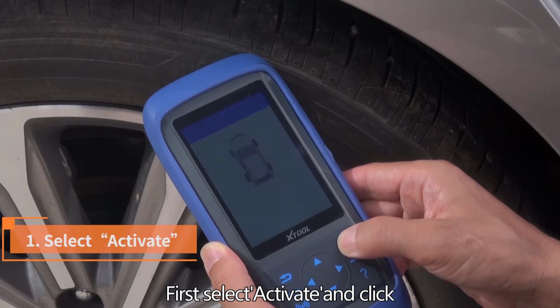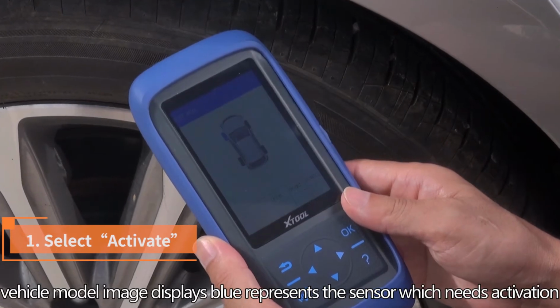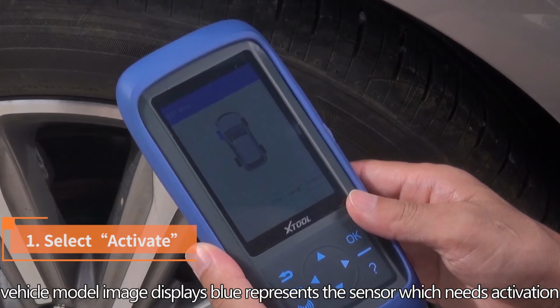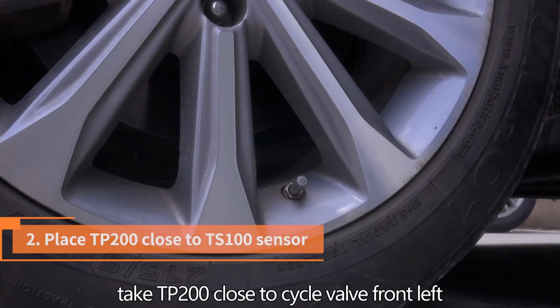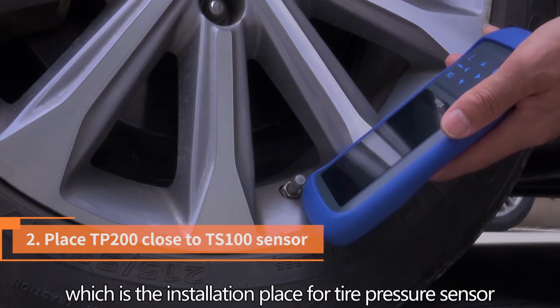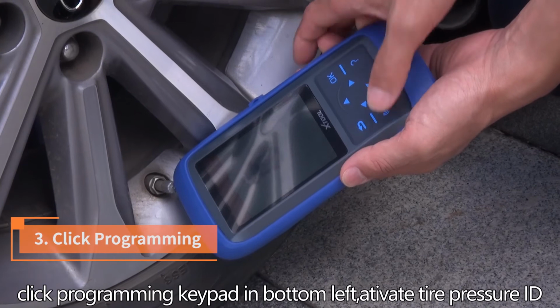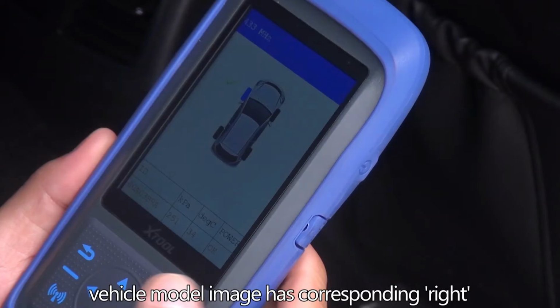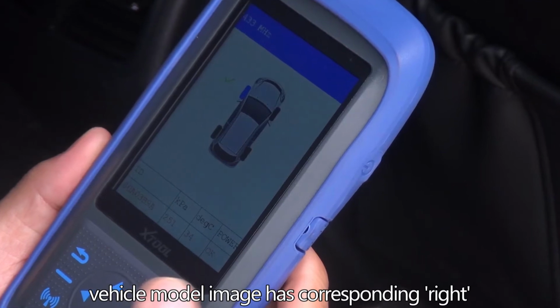First, select Activate and click. The vehicle model image displays blue to represent the sensor which needs activation. Take the TP200 close to the valve at the front left, which is the installation place for the tire pressure sensor. Click the Programming keypad in the bottom left. Activate the tire pressure ID. The vehicle model image changes correspondingly.